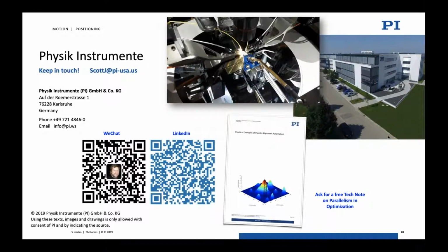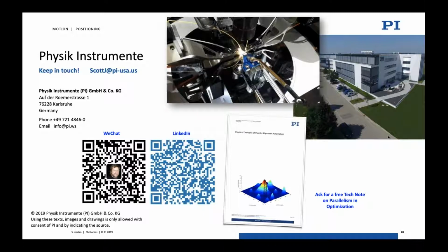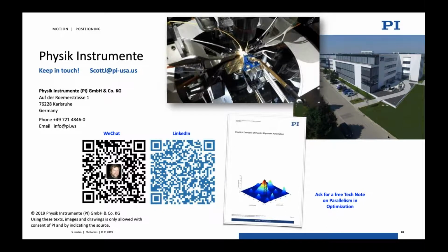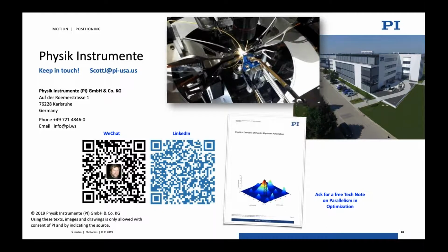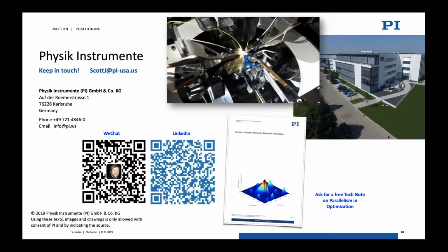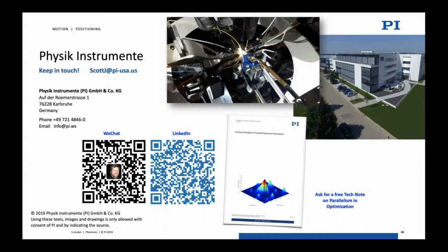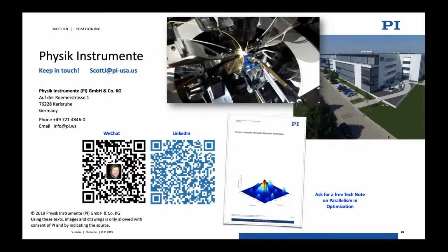I've worked with some where customers have said, I have the power meter, let's use this. And I'll try it and find it has like a 2 hertz analog bandwidth. And then they'll look at the manufacturer specifications and say, but it's 100 kilosamples per second. Well, yeah, you can rapidly sample a slowly varying signal. Unfortunately, most power meters are kind of slow. There are a few out there that are fast enough to keep up with this system. One is ours, another is the new Focus 2101, 2103 power meters, very fast. There are some others, some Keithleys and Keysights that in some models are fast enough and have the type of interfacing that we need.